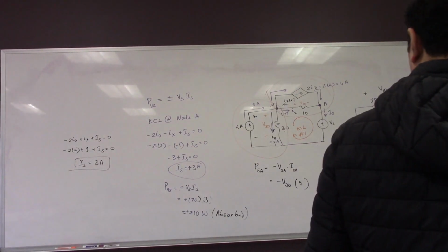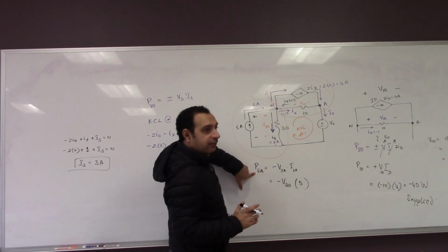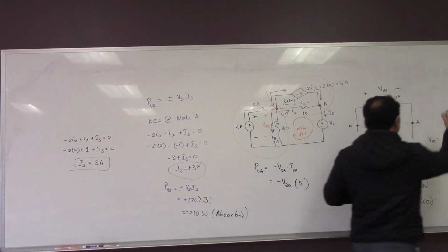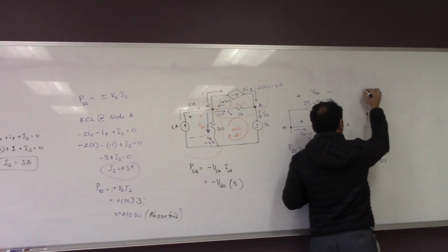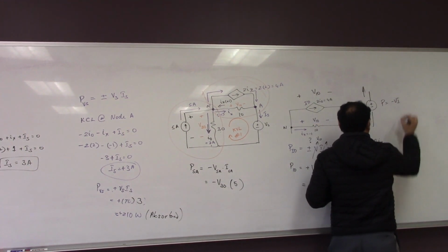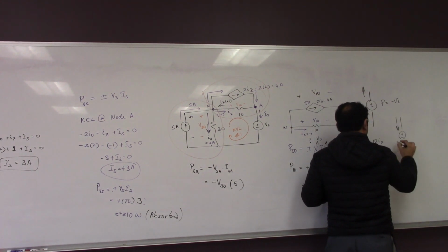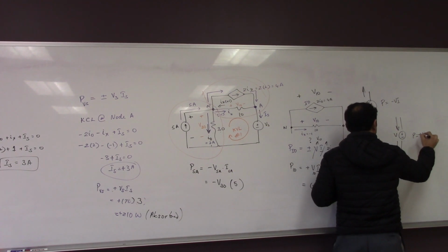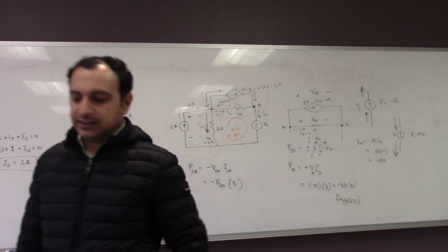Why is the voltage, the voltage is not negative. The power is negative. We are writing it because we need to pick a sign, plus or minus. If current enters the negative or leaves the positive, then power is negative. If current is entering the positive or leaves the negative, then power is positive. So depending upon which sign it enters, power will assume that sign.